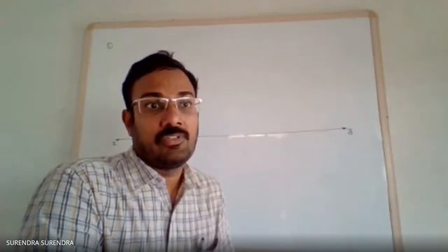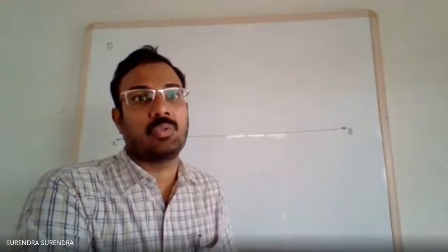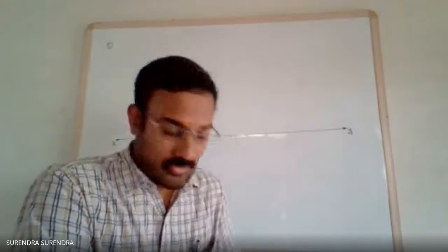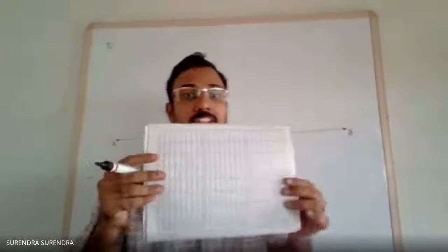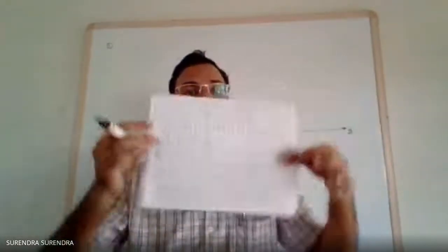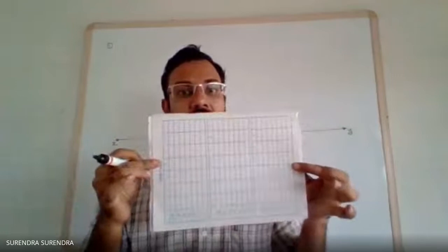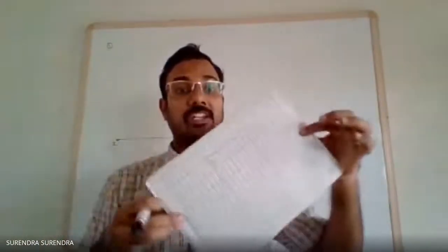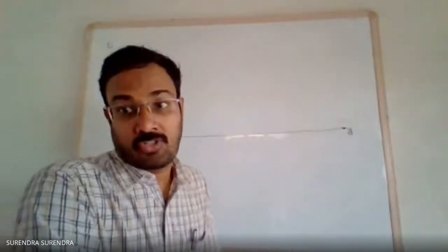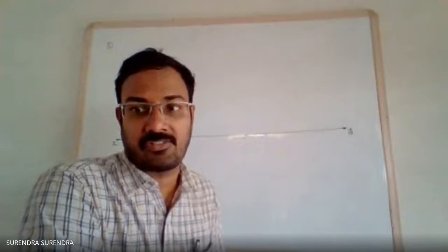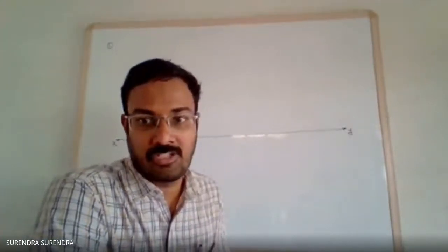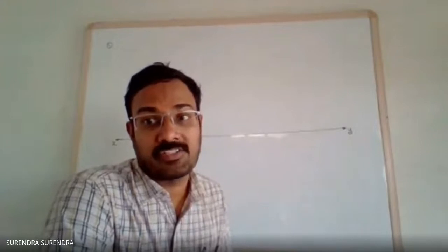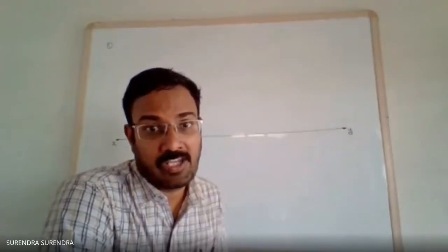In the front view, before drawing, check the other conditions, how it is oriented. Even though the surface is parallel, it may have different kinds of orientations. So along with the angle, we should also know the orientation of the surface. The condition given is: draw the projections and obtain its traces. Actually, traces are not in our syllabus, so there is no need to draw traces. The condition is: when one of its sides is perpendicular to HP.